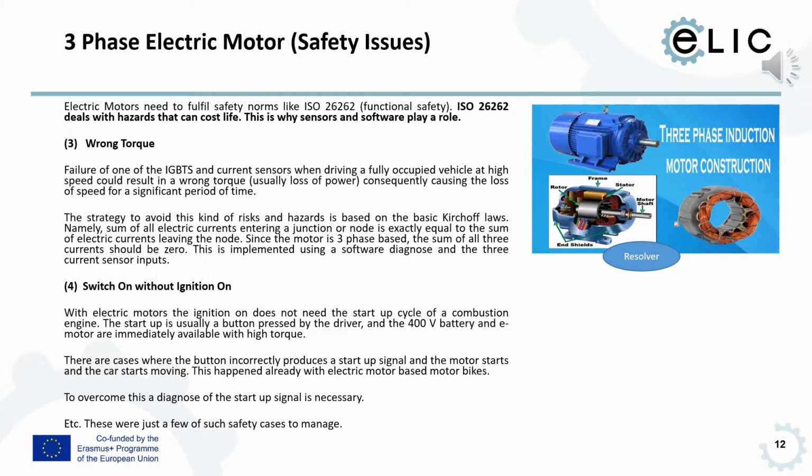And when you have immediate power, just imagine you have some electric car, you park it in front of a cafe, and then incorrectly the button has an electric fault and says switch on the engine, and then the car would start to accelerate. Therefore, this is a safety case to really recognize that the driver really has confirmed to switch on and wants to accelerate the vehicle because it could be a false ignition on.